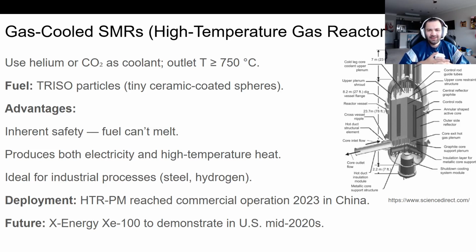The con with it, and what they use this helium gas for is to cool down the reactor. The problem with these high temperature gas reactors, HTGR, the gas-cooled reactor, is that helium is not a very good heat conductor. So they don't cool the reactor as well as other types of reactor, even water, right?